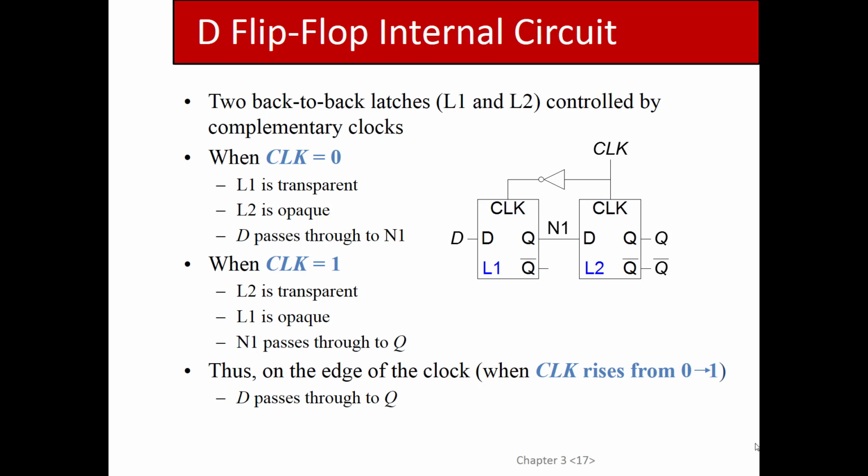Make sense? So to summarize, you start out with an SR latch, which is two cross-coupled NOR gates, which essentially are cross-coupled inverters, but there's that SR that allows you to get a bit inside of the cross-coupling, right, inside the loop.